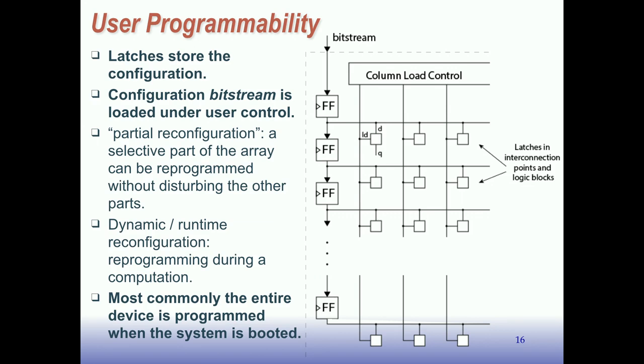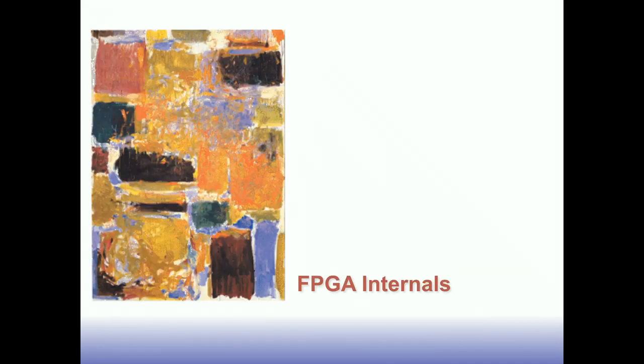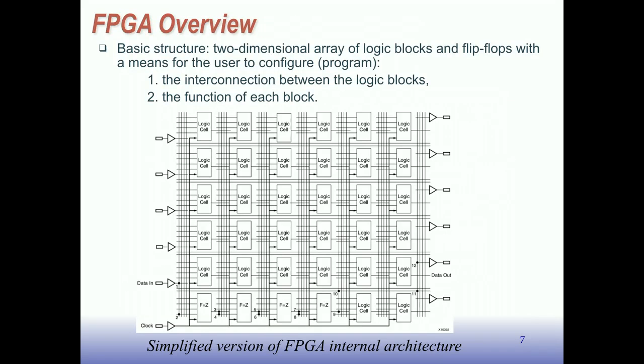Okay, now remember, back here, you have this model in mind, you have all these connections. So we talked about how to make these cross-point connections, right? How they're fabricated on the chip with switches and latches. The switches are just MOSFETs. So now we're going to look inside a logic cell. And we need a logic cell to be designed in a way to give us flexibility, so we can let it be anything we want.